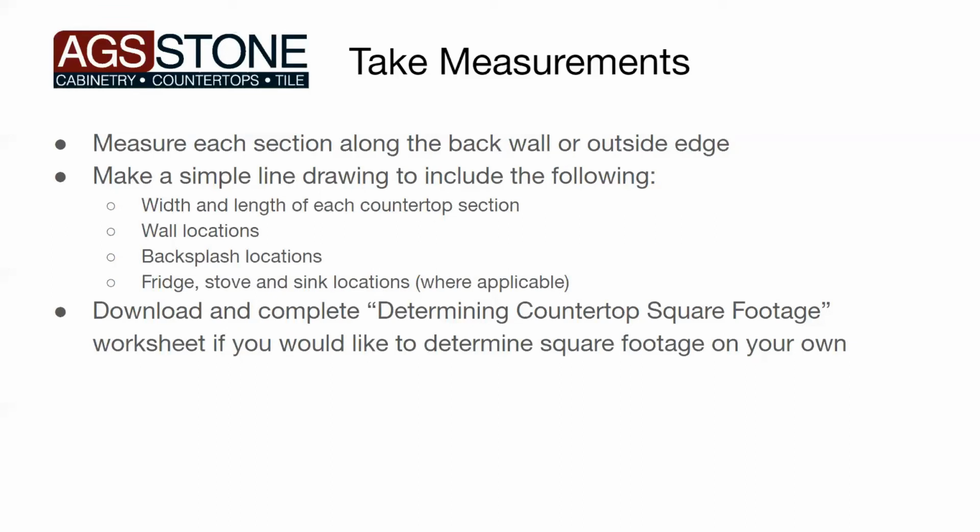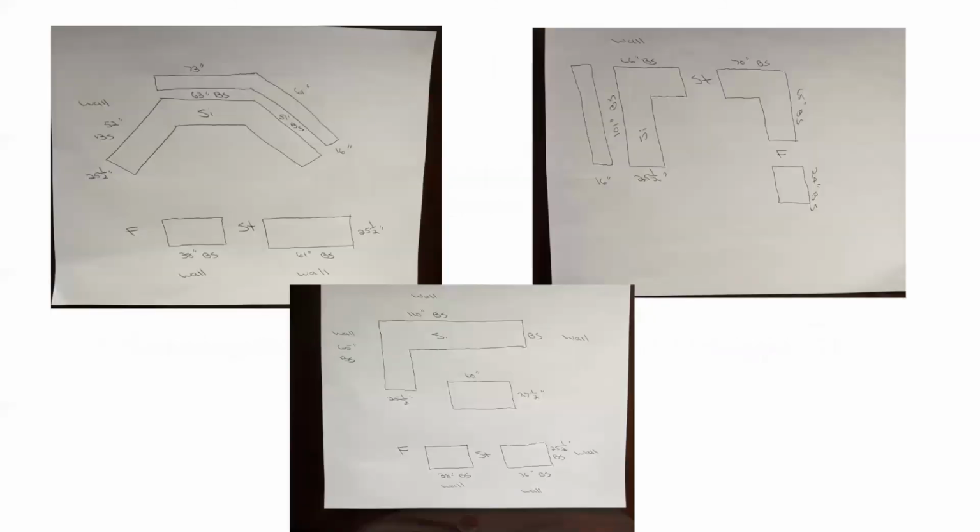And before you actually start measuring, you'll want to put together a stick drawing. And I'm just going to bounce ahead here quickly and show you what I mean. Very simple, crude stick drawing, which is an illustration of your countertop layout. And I'm no artist, as you can tell, but you see that these are just a very rough sketch, which includes dimensions and some other basic information that will help us in determining countertop square footage at this stage in the process.